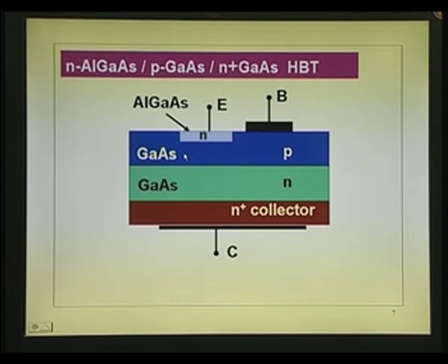So the aluminum gallium arsenide emitter is actually what you can call a generic HBT. The first heterostructures used were AlGaAs on GaAs, because there is good lattice match. So gallium arsenide is 1.43 and this can be 1.73, so you get 0.3. So you get a beta which is very high. This is the schematic diagram which I have shown.